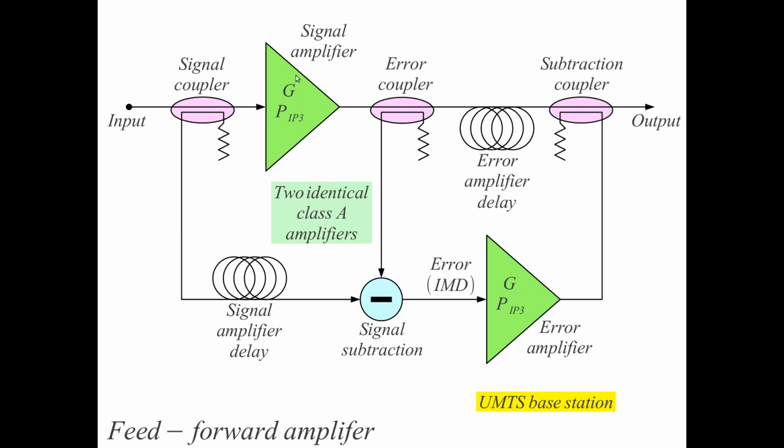But it is very inefficient. I need two Class A amplifiers here. I need very accurate adjustments of the delays introduced by the amplifiers, of the group delays introduced by the amplifiers. It is very power inefficient.